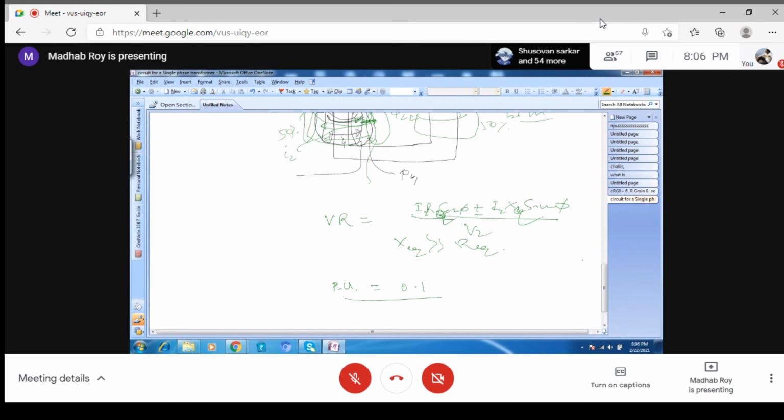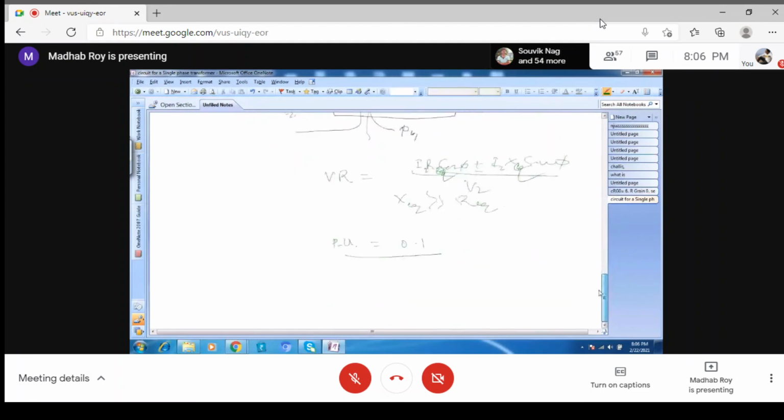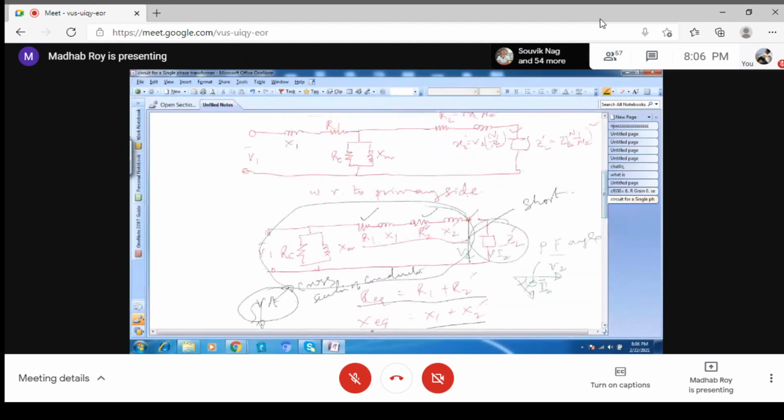Now another thing we have to discuss. Sometimes leakage reactance is deliberately kept large. Now we are going back to the question we started with. Suppose there is a short circuit here instead of load, and you know that these values are very small. We have already designed very small values of X1 and X2, and R1, R2 are naturally small. If somebody by mistake applies the rated voltage under the short circuit, what will be the case? Do you know that very large current will flow?